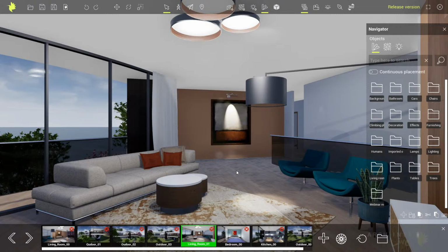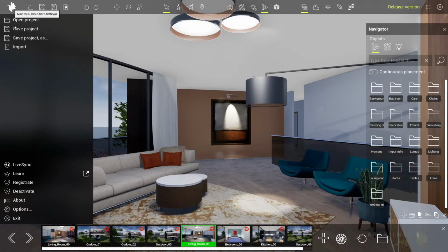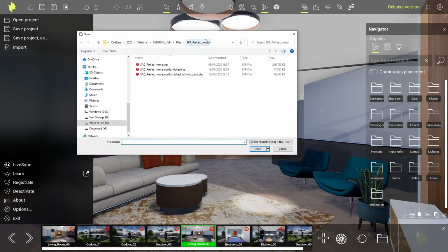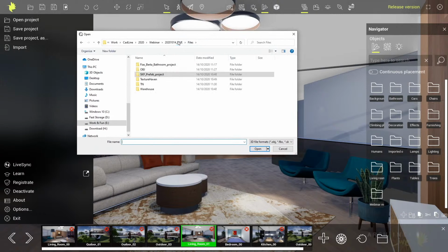Once you have an object like that, you can go to the main menu of Live, and then you can use the import command, this one. Once you open up that option, you end up on your hard drive, and you can go to the library of yours, and then you have something either received from someone or downloaded. In my case, as I use the 3D Warehouse, I have downloaded a few things like benches, and also I downloaded a smart vacuum cleaner. This is what I want to load now.